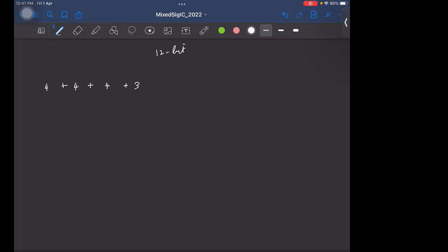So how many bits of resolution will this realize? I mean, this is the first ADC resolution, this is the second ADC resolution, and so on. And let's say I'm having 1 bit of redundancy in each stage. So what is the overall resolution? 12. Okay, this is 3, 6, 9, and 12. Or I can also realize the 12-bit as just having a 6-bit plus a 7-bit, right? So this is giving 6-bit.